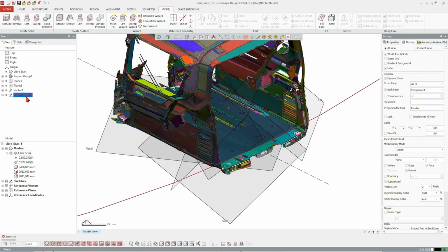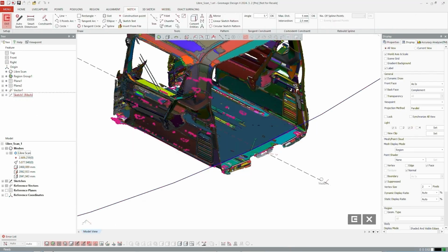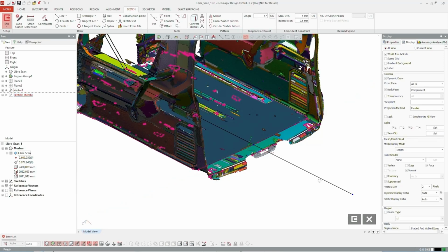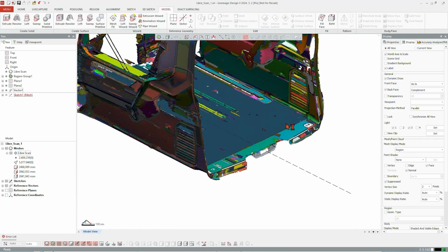So by rolling to end, the sketch is available, and by editing the sketch, we can simply convert this vector into a sketch line and generate a point right at the intersection of the circle and the line. Now, since we have the point available in here right now, line and circle are not needed, so we can delete them right now, which helps us sort out the position of the wanted origin.